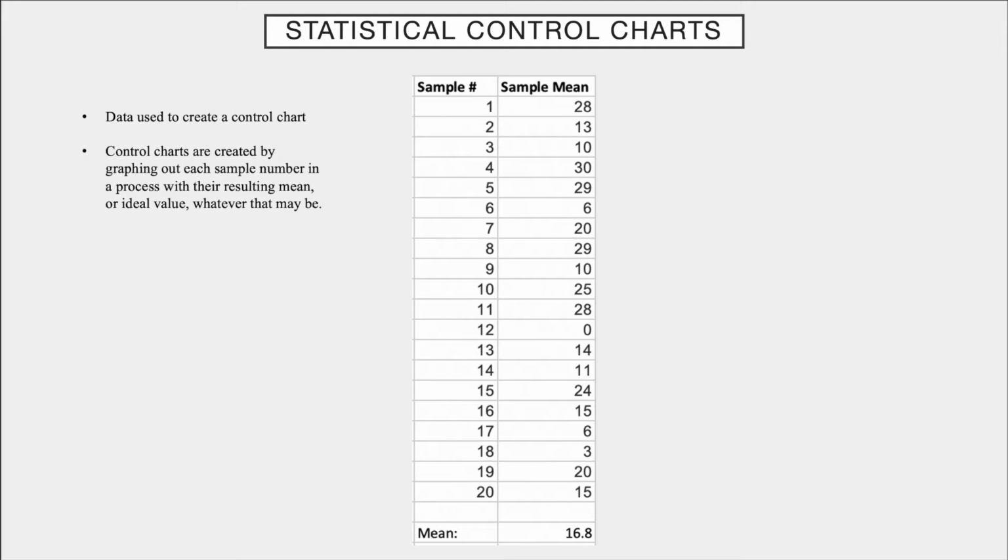The resulting graph should look rather jagged, which means that each point on the graph is independent of one another and no pattern among them should be noticed. It is crucial that each test is independent of one another because relationships among the tests could skew the data by not showing as many outliers or showing more outliers than there truly are. This would defeat the whole purpose of the control chart because its goal is to display whether or not a process is in control and if changes need to be made.